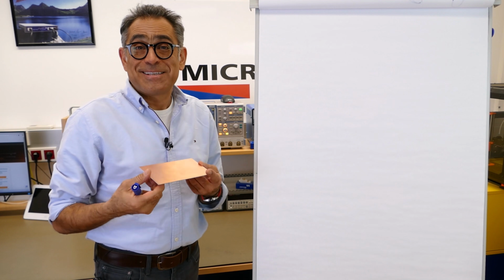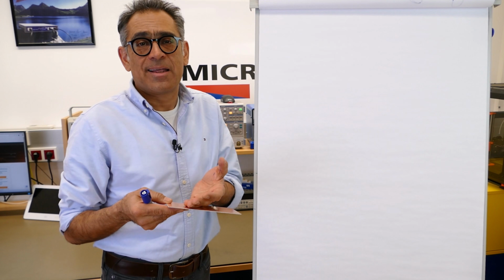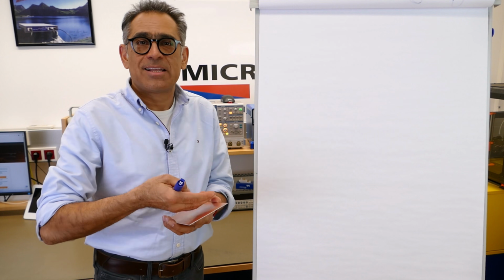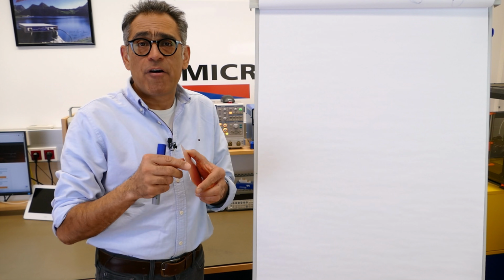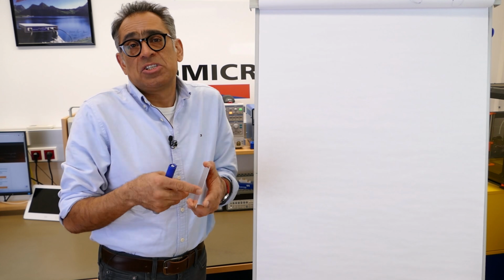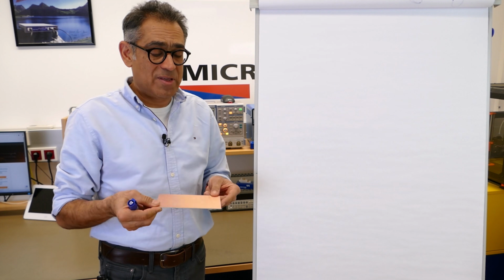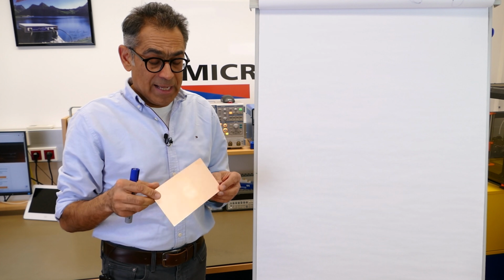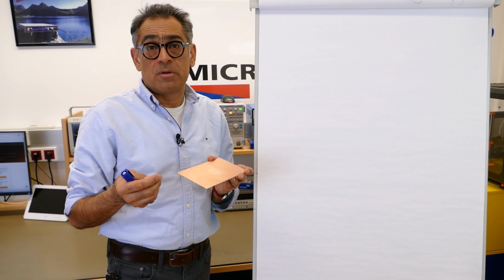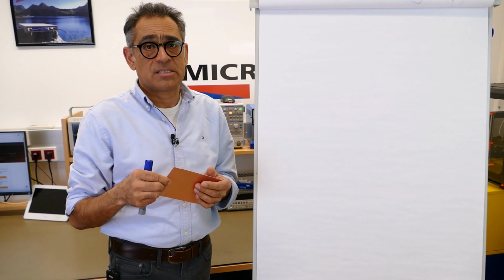And of course, this is exactly what happens on our PCB. You have got a top layer, that is copper. You've got a bottom layer, that's probably, let's say, your copper core for your ground perhaps. And you've got this FR4 material in the middle, which is an insulator, which will be the dielectric. So whether we like it or not, we have got some parasitic capacitances on our PCB, and therefore a signal can get from one point to another via this capacitive coupling.